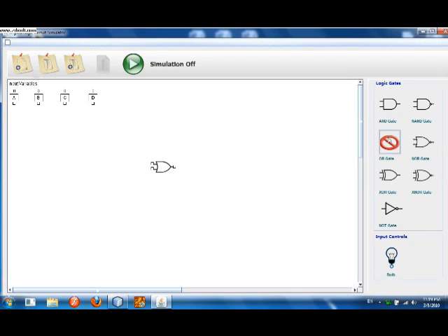You might be asking, hey Rolf, what's with the click thingy? This is to make it convenient for you if you want to add a lot of logic gates in the canvas. For example, you want to add this AND gate and you want to add it again. Just have to click it again anywhere in the canvas, then deactivate it.